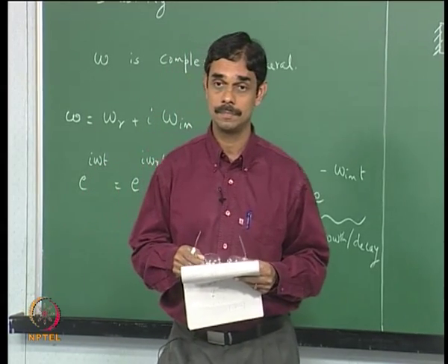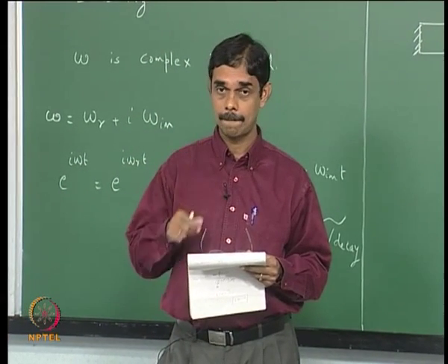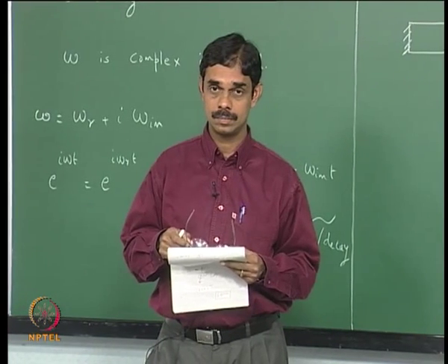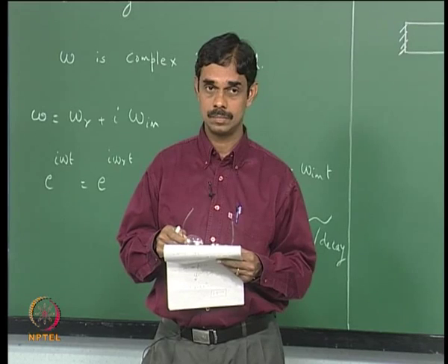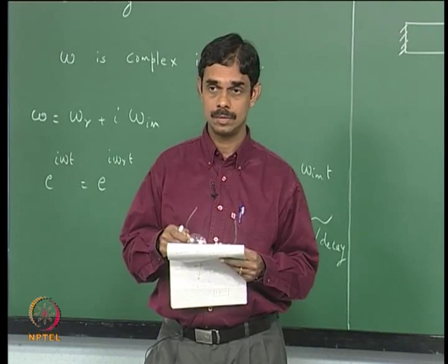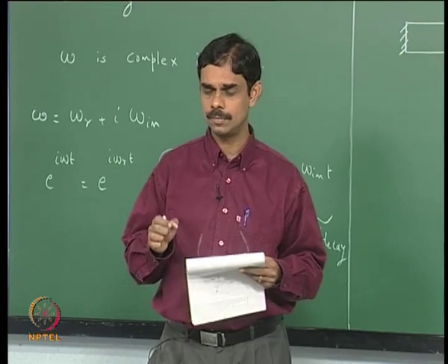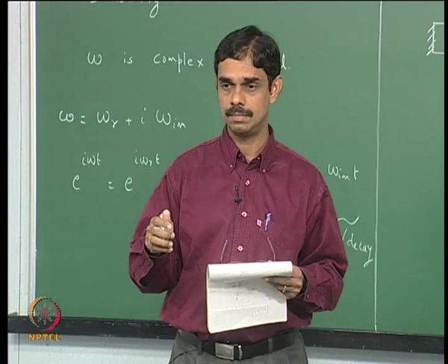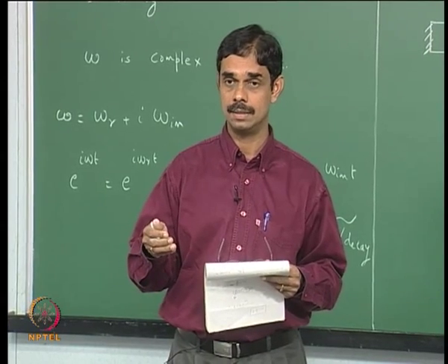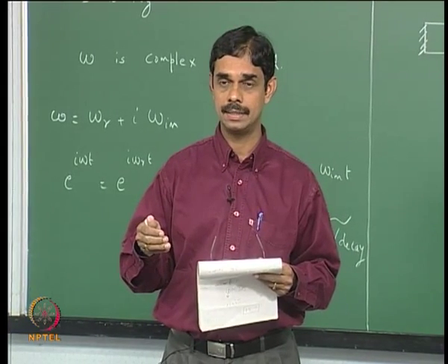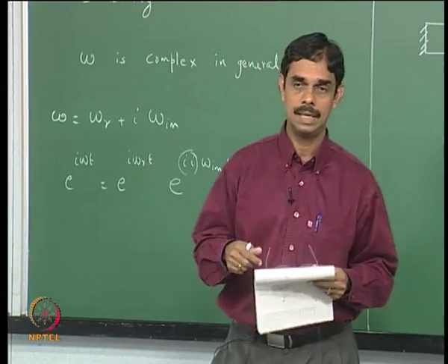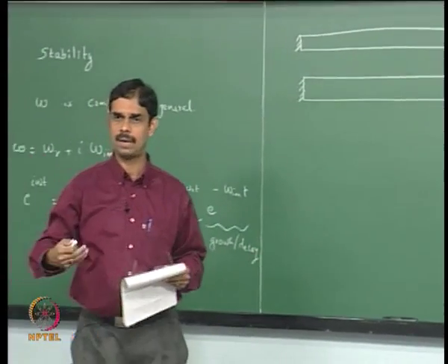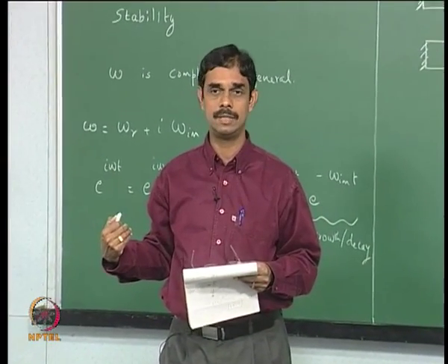Yes, Vishnu. Yeah, for acoustic velocity we generally take it as adiabatic traveling waves, but when we add energy there, that velocity will change, no? That is, if you are talking about a small particle and you are able to add energy by heat energy or something to the particle, but we are not speaking about adding energy there, we are speaking about leaking in acoustic wave. So in terms of an intensity flux coming in at the boundary, that is the way we are thinking about adding energy.